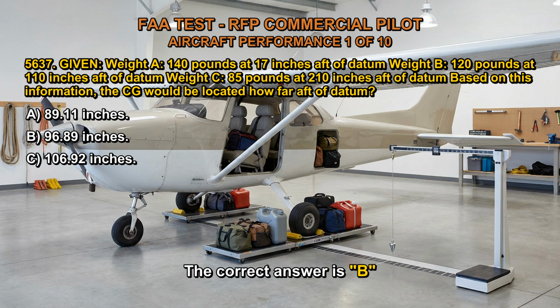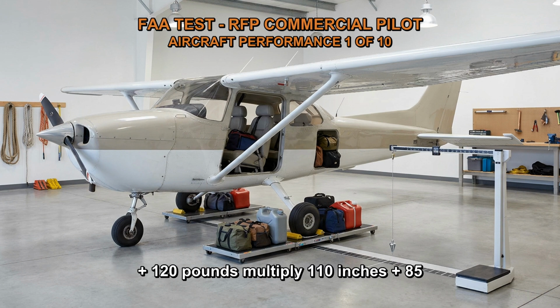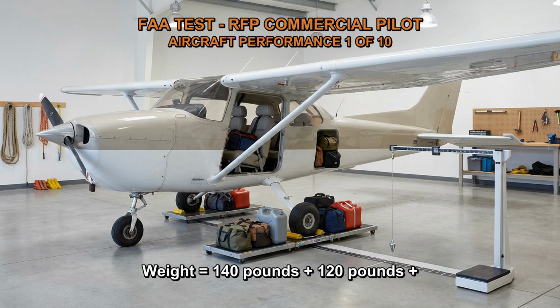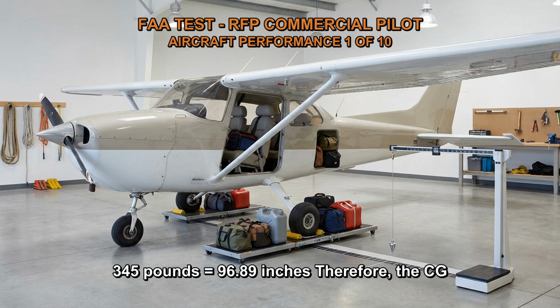The correct answer is B. Total moment equals 140 pounds times 17 inches plus 120 pounds times 110 inches plus 85 pounds times 210 inches equals 39,820 pound-inches. Total weight equals 140 pounds plus 120 pounds plus 85 pounds equals 345 pounds. CG equals total moment divided by total weight equals 39,820 pound-inches divided by 345 pounds equals 96.89 inches. Therefore, the CG is located 96.89 inches aft of the datum.